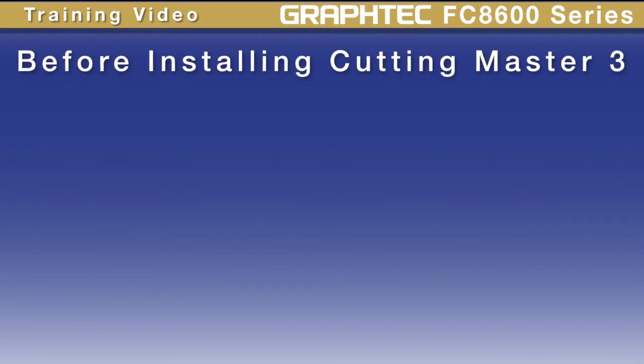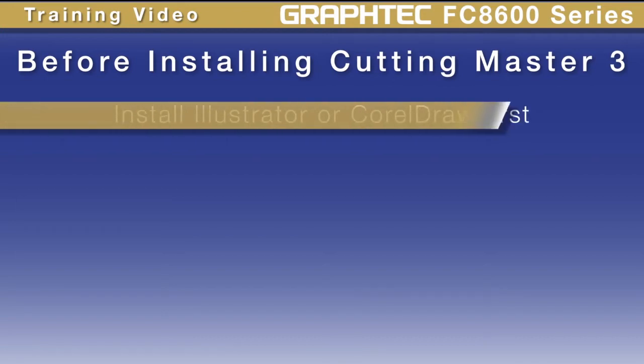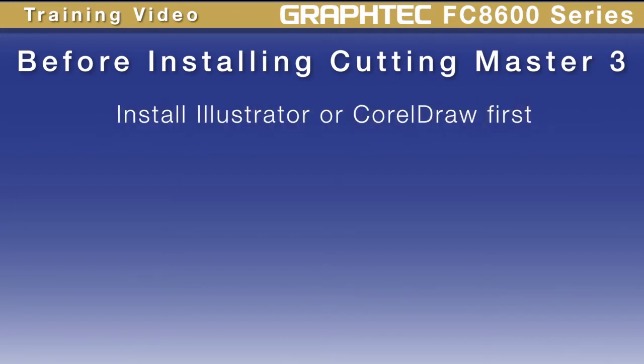Before installing the software, there are a couple of steps that must first be taken. When installing Cutting Master 3, the installation program first looks for the location of where Adobe Illustrator or Corel Draw is installed. This means that these programs have to be installed prior to installing Cutting Master 3. The first step is to install the graphics application you plan to use, whether it is Adobe Illustrator or Corel Draw.